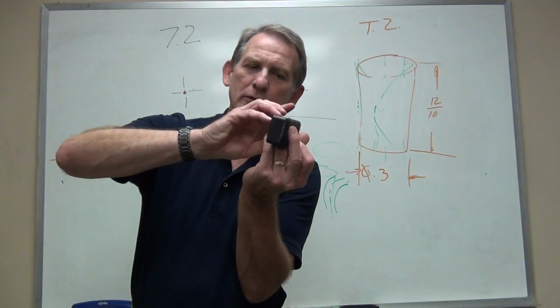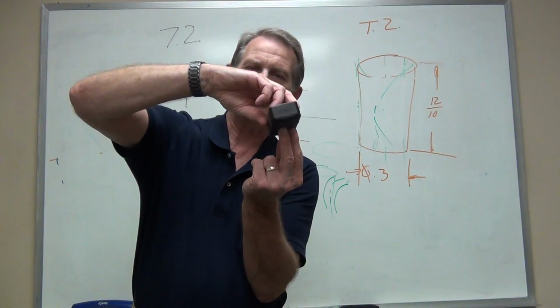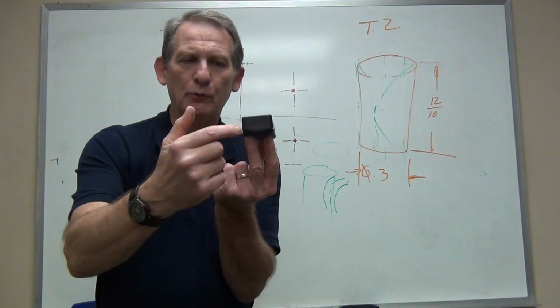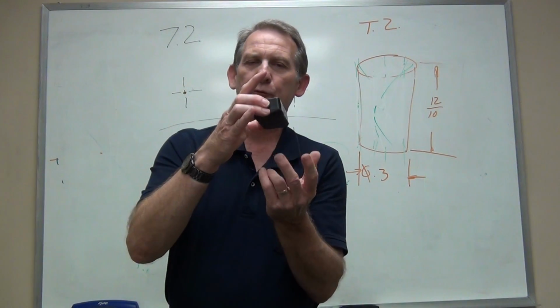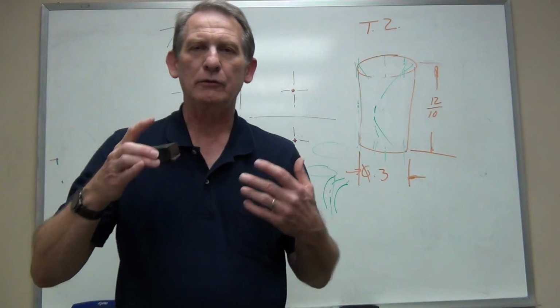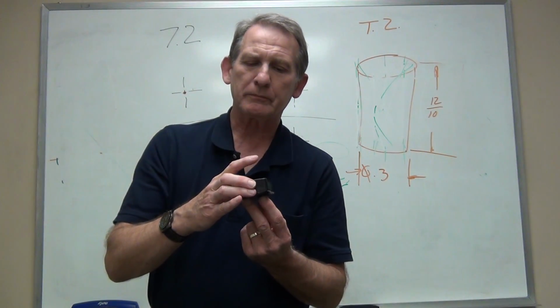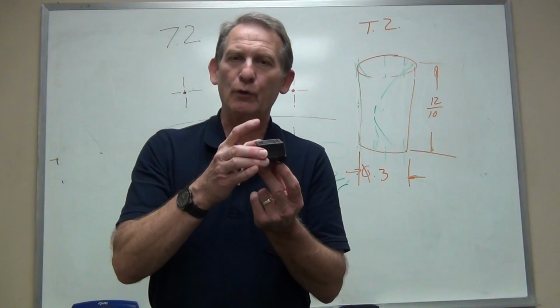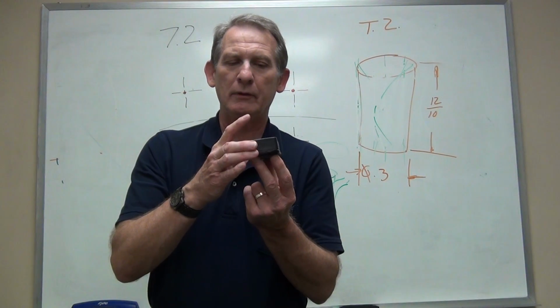I can still translate this way. So if I put 2 points here and 1 point here, I will have fully constrained that part. So I'll use 3 datums to do that.